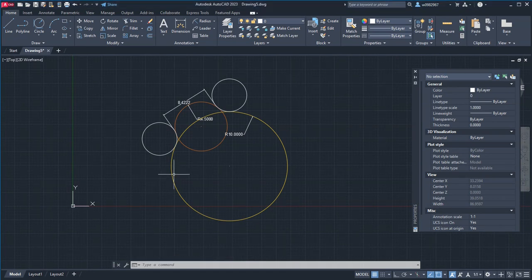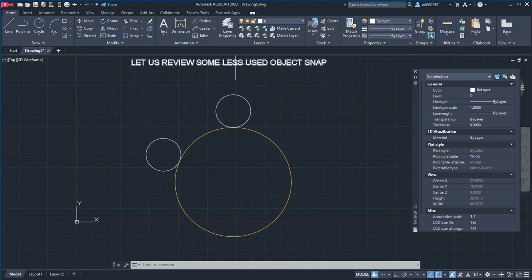All right, so this is very important. Using tangent, tangent, radius is one of the important things in AutoCAD because this one will allow you to do curved parts for engineering. Let's erase these dimensions and we're going to arrange this orange circle. If you wanted to create an engineering part where they're all made out of curves and circles, we can use this circle and copy that exactly on this location.